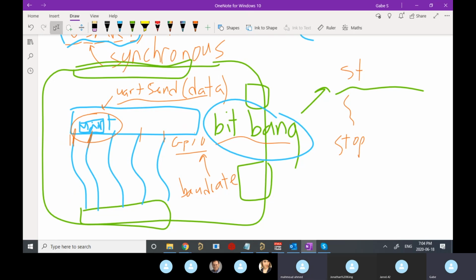Yeah, I think so. Because UART is a hardware thing, right? Yeah, almost all of these have SPI, I2C, CAN. They'll have a hardware controller inside with registers, interrupts, buffers, shift registers, all set up ready to go to do it really quickly. If you do it yourself, it's going to be a lot slower.